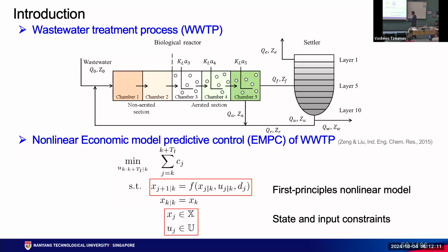The objective has dependence on 23 state variables, and this process contains 145 state variables. To solve the optimization one time using IPOPT in Python, if the control horizon is 15, it takes 5 to 10 minutes, providing that you have provided a good initial guess. Okay, and more importantly, time is not the biggest concern. It's a concern, but not the biggest. The concern is that the solution is just comparable to set point tracking MPC. So we just believe that it converges to a local optimum. We are not experts on optimization, but it's just our guess.